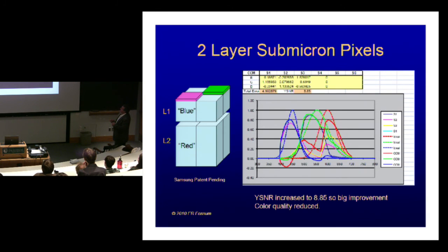Anyway, here's an idea that I was working on, which involves kind of an in-between approach. We have 2 layers as before, and we have 4 pixels though, and we let white light come in through these pixels and green light into that pixel, and this pixel with a magenta filter just allows blue and red through it, blocks green. And we can say that the blue is absorbed in this layer and the red is absorbed in layer 2. So we get at least 3 pixels that have a very strong luminance signal, and just basically one of those 4 pixels is used for the chrominance signal, the blue and the red signal, which we don't care so much about the noise in those signals. We care mostly about the noise in the luminance. And again, if we work through what we start out with and going through a color correction matrix and calculate what the signal to noise ratio is, we see that the signal to noise ratio increases to maybe 8.85 or 9, which is very close to what the customer needs.